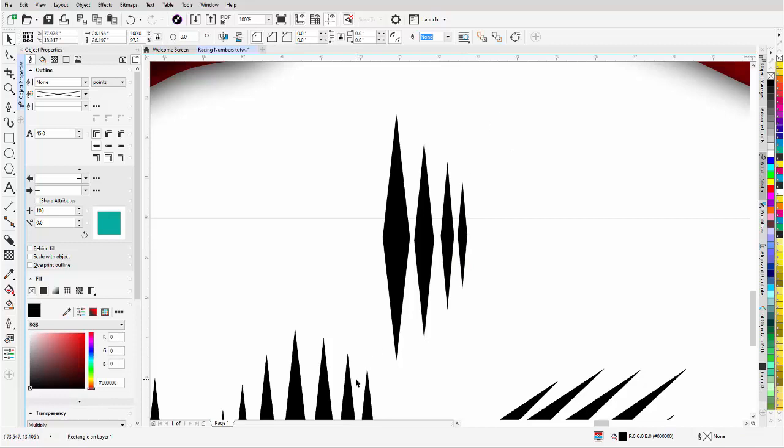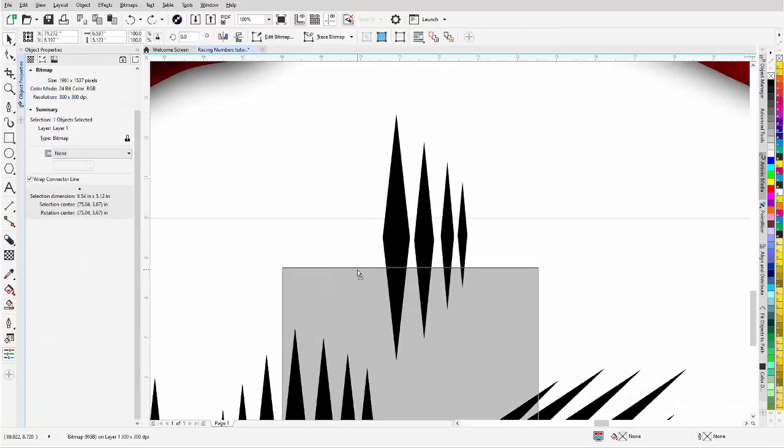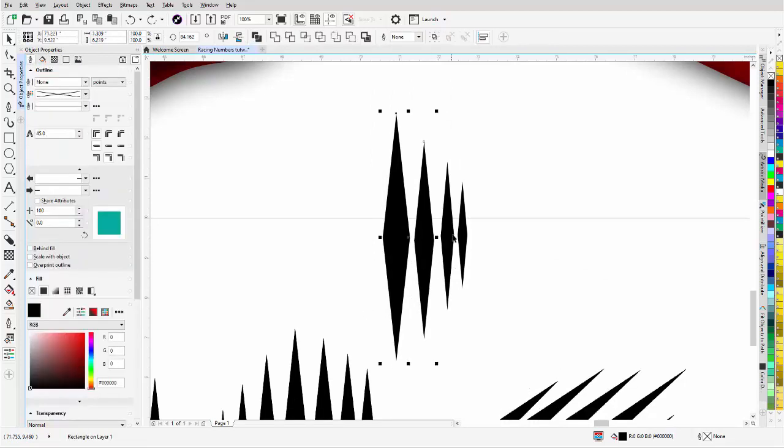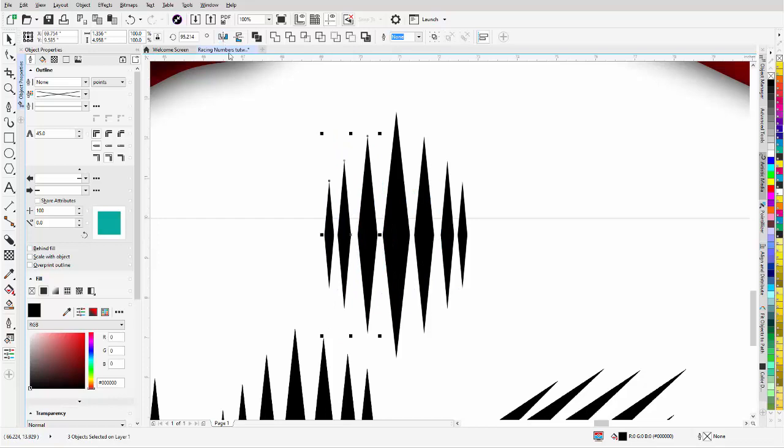I'm going to select everything here, and I grabbed something by accident there. So I'll start here at the bottom. Well, I got another object there. So just hold down Shift then. Shift, Shift, Shift, select all four. Hit the E key to align them horizontally. Take these three, bring them over here, left click, right click, duplicate one time, then mirror those. Get them nice and close.